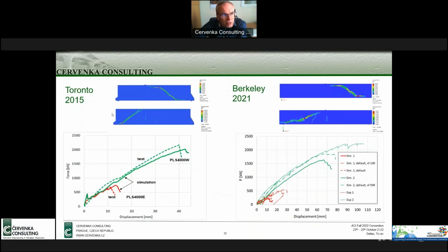So let me show the results. This is the Toronto test 2015, where we had a very good prediction and we were the winners. And these are our results from the Berkeley experiment 2021, where our results were not so good. One of the reasons, which we evaluated afterwards and learned from, was that we wanted to really be on the conservative side in our predictions. So we took into account quite significantly the shrinkage effect, and this very much reduced our prediction of the load carrying capacity. So this is something we learned, that in these experiments, the contribution from the shrinkage to the cracking was not so significant.